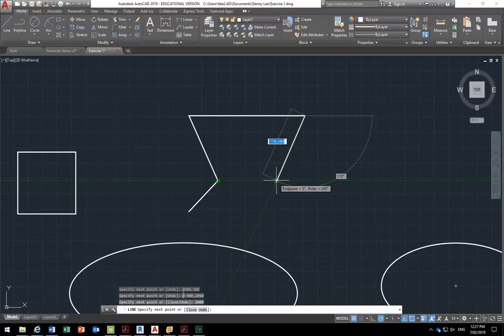And what's the number? 1158.465468. Who cares? We don't have to do the maths. AutoCAD does it for us. We just need to understand how we're getting to these points. So as long as I've got the 245 degrees and I'm projecting from that other point, I'm going to get a line that's the length I want.